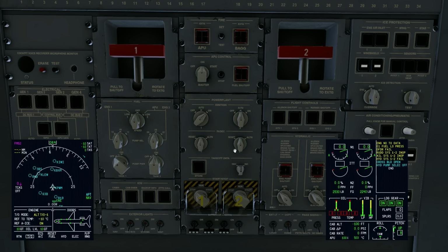All right, moving on, we come down to our start-stop selectors, and these are similar to the APU master in that these are how we interact with the FADEC, what we're asking the engine to do. So obviously, we ask it to stop, we ask it to start, or we ask it to run. A big gotcha with this, and what they teach us, is that these are a request, but the actual indications on the EICAS are the truth. The reason being is there's one big gotcha in Embraers, and it's a safety feature, but it can bite you.